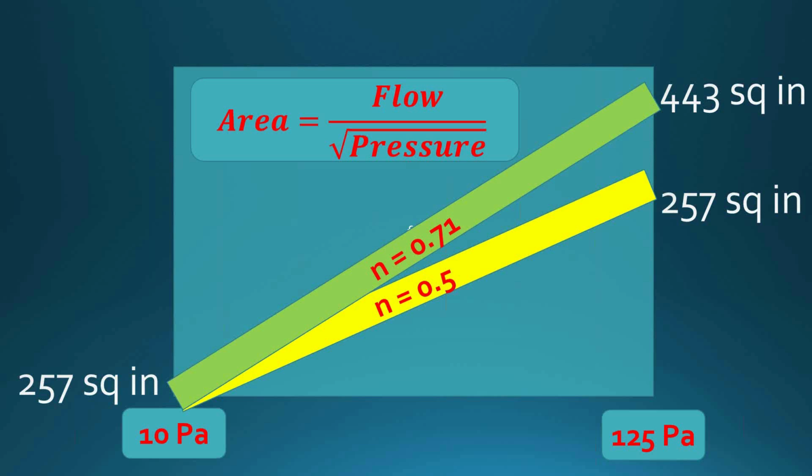Now, if we were to go in the opposite direction, we would find that for low pressures, around 1 pascal or so, which is where the inert agents leak out, the enclosure is actually tighter, or apparently tighter. So we get a more accurate prediction of the hold time and a more accurate prediction of the peak pressure, and both of them are less conservative than they were before.